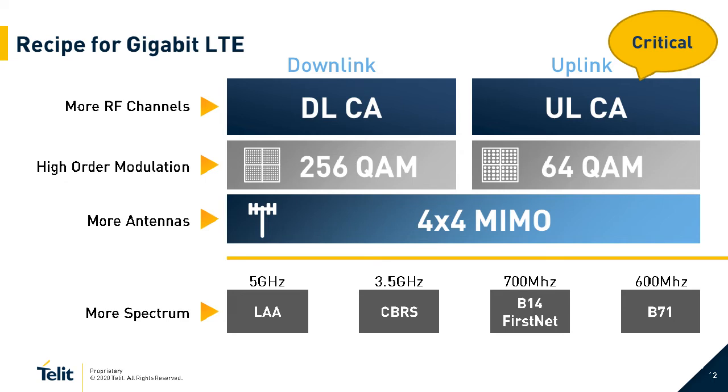And last but not least, the third ingredient is called MIMO, which stands for multiple input, multiple output. And essentially here what we are talking about is the use of 2 or more antennas to basically send more data and also achieve the spatial diversity and leverage copies of the same data that reach the receiver and has a higher chance of getting a successful transmission. So with the Gigabit LTE, the provision is to allow up to 4 antennas, both on the transmit and the receive. So these 3 ingredients basically provide you a recipe for Gigabit LTE.